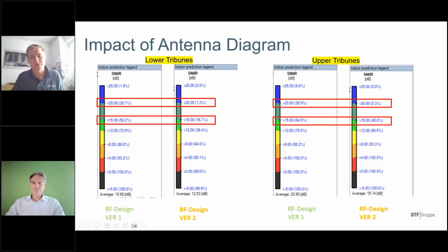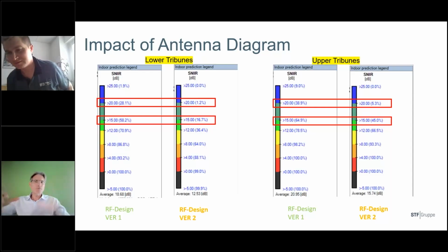Which design to prefer? Of course, if, for example, this antenna change is causing you to have less SNR, maybe it should trigger you to think, do I need overall a 5G antenna and a 4G antenna together? Maybe it would be better to have just a 5G dedicated antenna and not lose on the LTE side, which I personally prefer. Yeah, in most cases, on a catwalk installing antennas, they are all large, heavy antennas, and adding 2 antennas instead of 1 might not be possible because of the load.